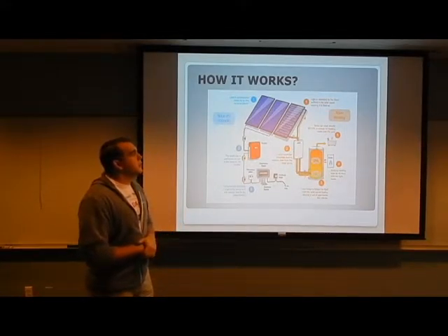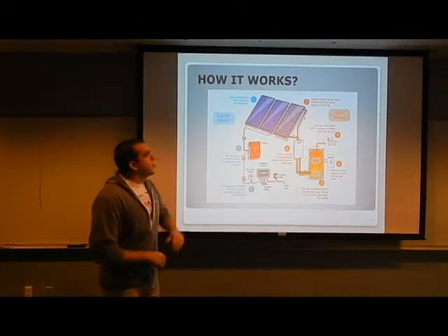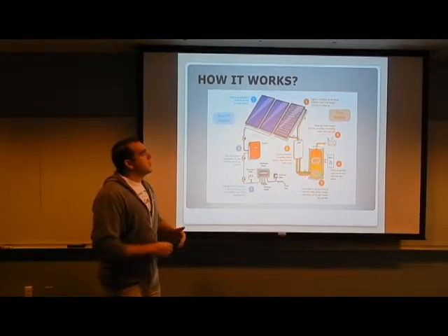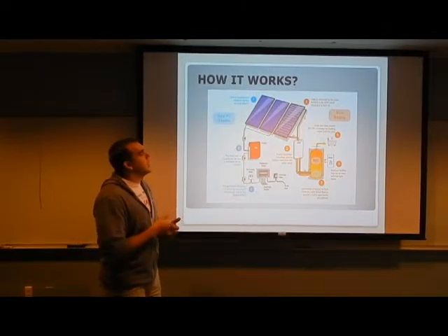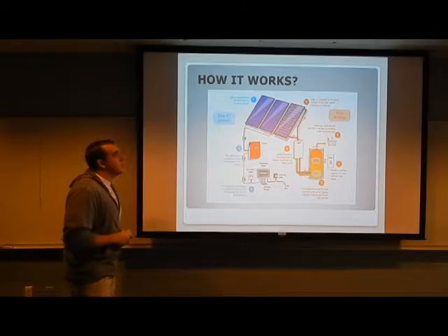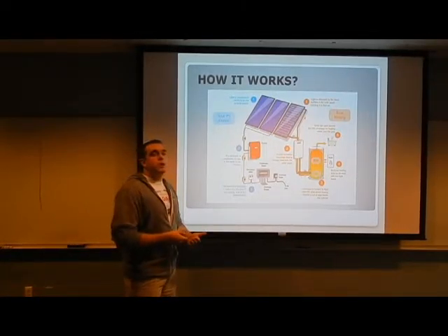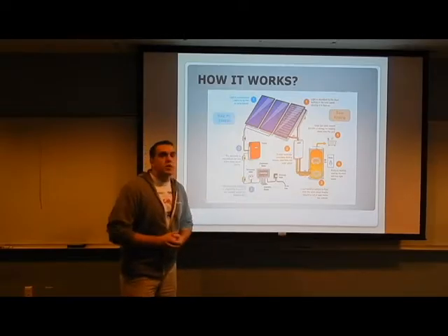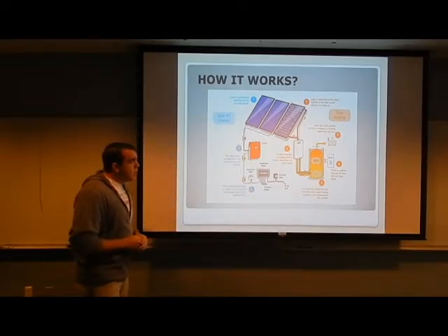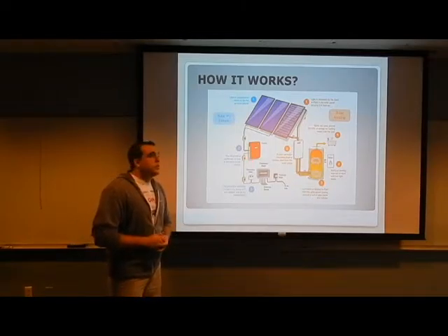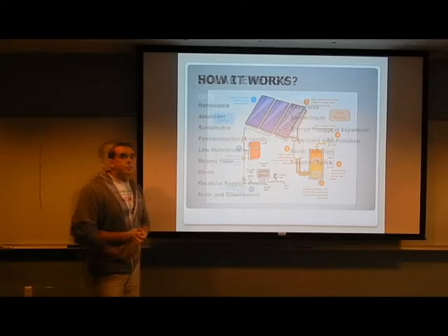On the thermal side, we can see an array of copper tubes with water flowing through it, which is implemented inside of the solar panel. The light is absorbed by the black surface in the solar panel, causing it to heat up. Now the water absorbs this heat, and it can be stored in a storage tank for daily use. Solar can save around 60 to 70% of energy during heating throughout the year.